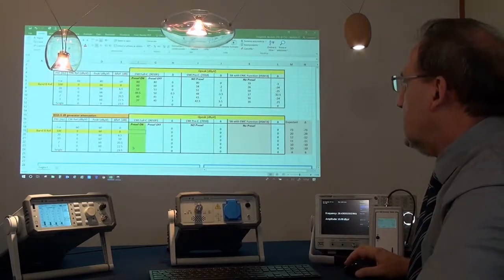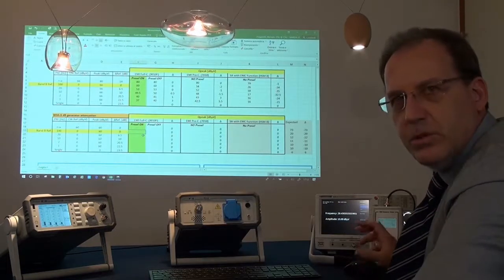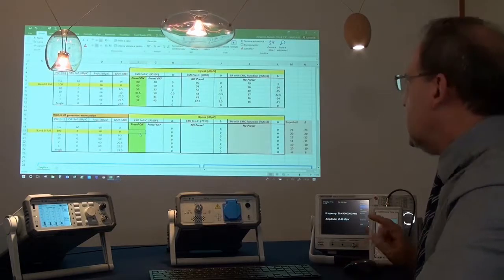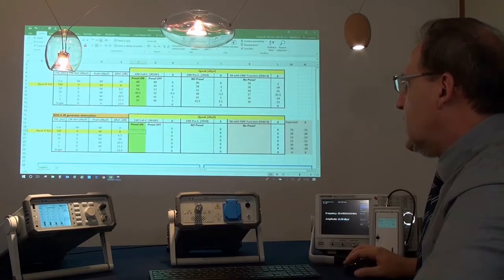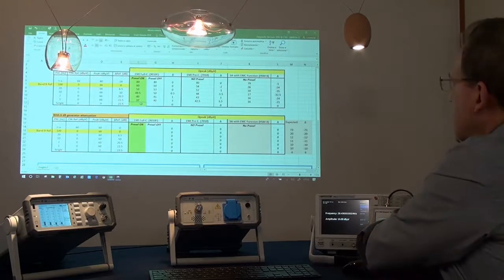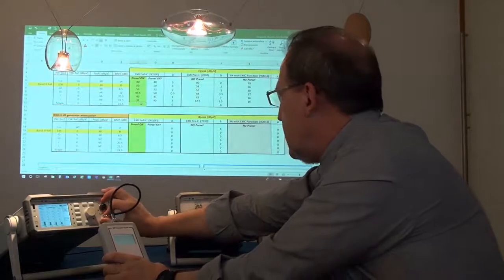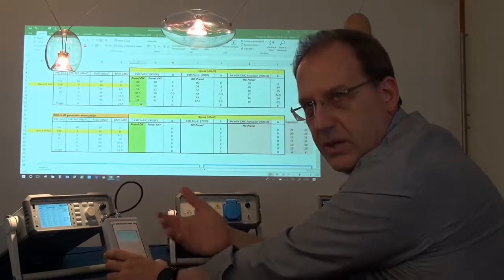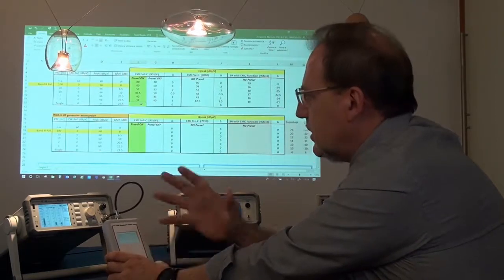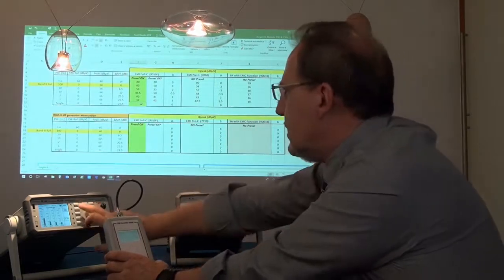We can also perform another test, so we can reduce the amplitude by 6 dB, and we can see about the sensitivity. But first, before doing that, we have to check the single pulse that we left behind us. So for the single pulse, we need to set a hold time that should be much higher than 1 second. The standard is saying you can use up to 15 seconds. So let's say already with maybe 6 seconds we can measure something.